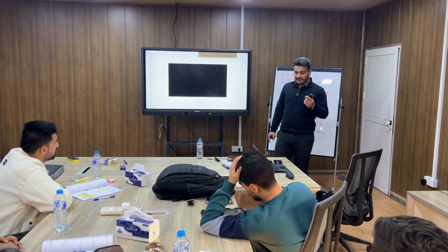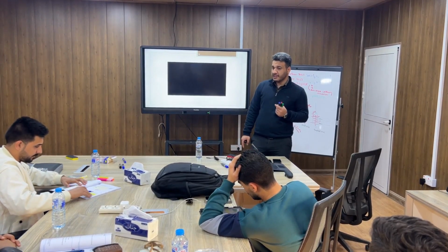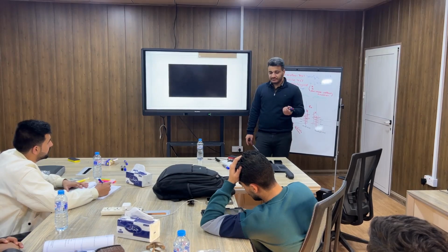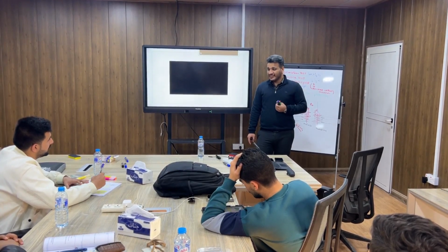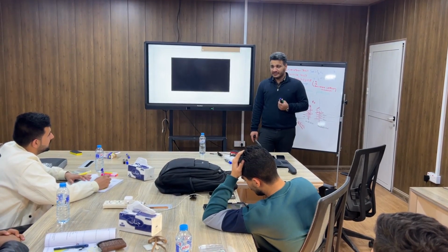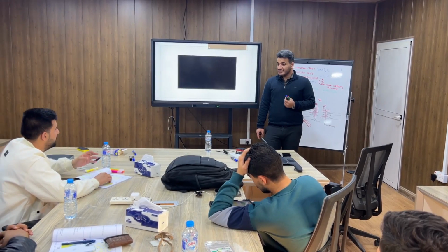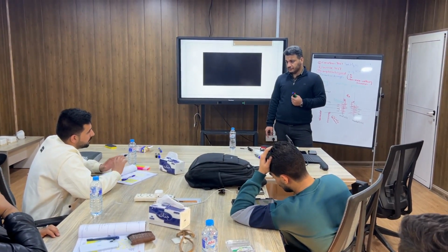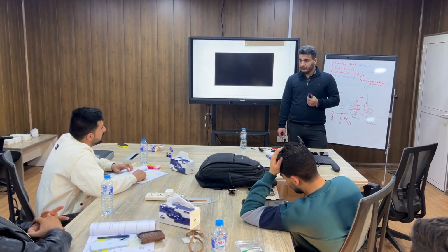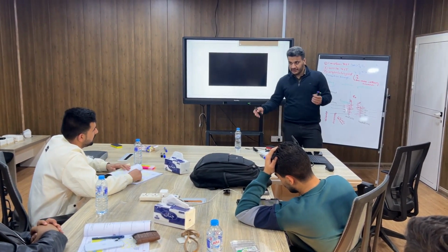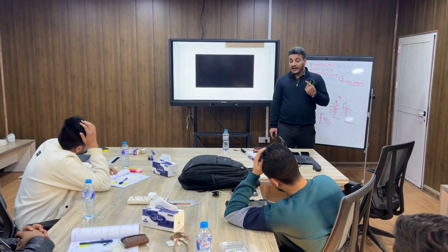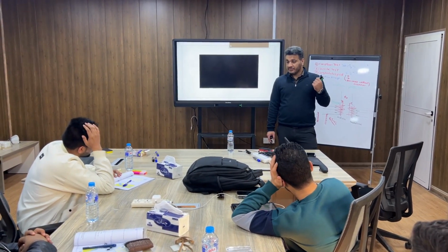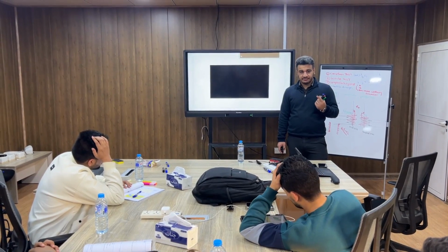But I have a different mechanical type during the drilling and the production, like the zonal isolation technique. Yes. Do you remember the zonal isolation technique? Like the swellable packer, swellable, inflated casing pressure. Yes. The swellable acts with the water and oil, and the elastomer is inflated and controls the zonal isolation. Another way to control the water from the aquifer is to inject cement.